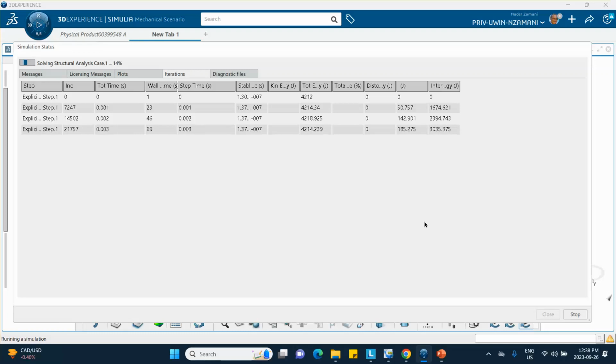The only caution, the warning that I give people who use these explicit solvers, is that it never fails. It always runs. It always gives you colors. It always gives you a number. It's just that, do these numbers and colors agree with reality? And that is a different ball game. Getting the stuff to run is not an issue. But whether these numbers make sense, whether these colors make sense, that is completely different, a different league.